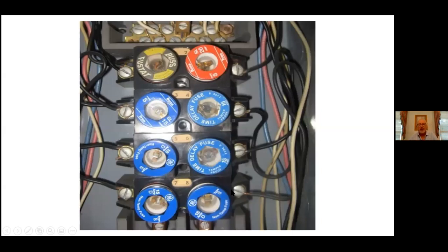What's happened here is we have an electrical panel that is too small to handle whatever extra electrical has been added in. And so they've gone ahead and put in these extra wires onto that particular fuse. Now, bear in mind that you can see these are all 15 amp fuses right here, the blue ones. The larger one is a 20, and there's a 30 up here. So you can't take a 20 and put it into the 15 amp fuse spot. They're sized differently. So the actual section that makes contact inside of this panel is smaller on the 15 than it is on the 20.